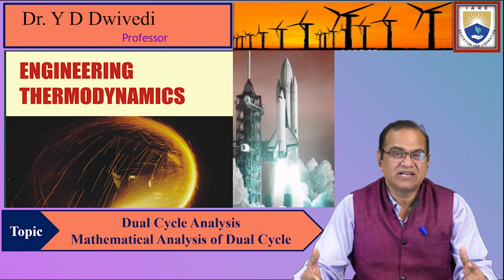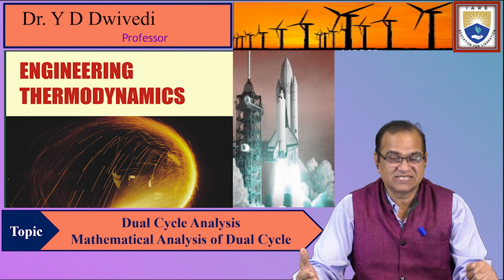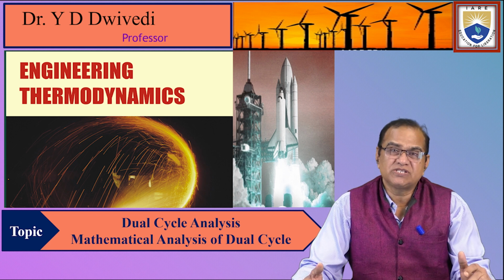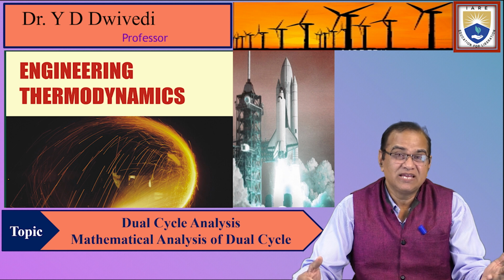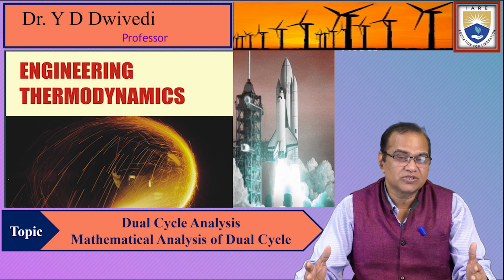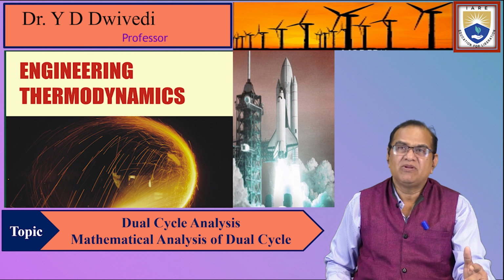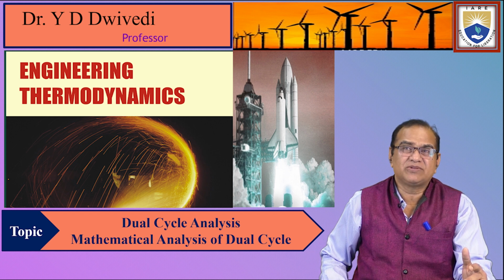We have also seen the effect of the cutoff ratio, that is rho. As you increase the cutoff ratio, the efficiency of the diesel cycle decreases. So how much is optimum is required? Next is the dual cycle. The dual cycle is a combination of the Otto cycle and the diesel cycle. Today I will be discussing the mathematical analysis of the dual cycle.